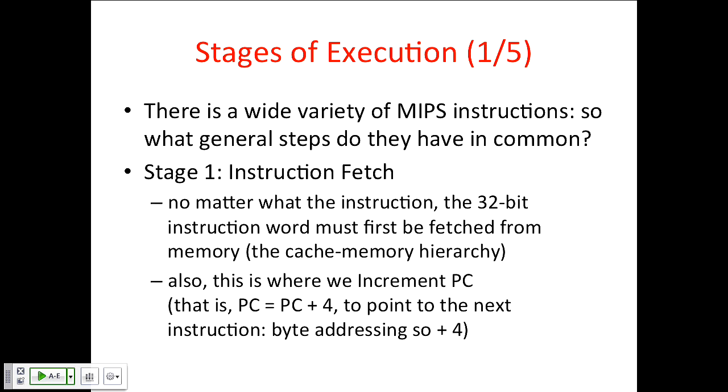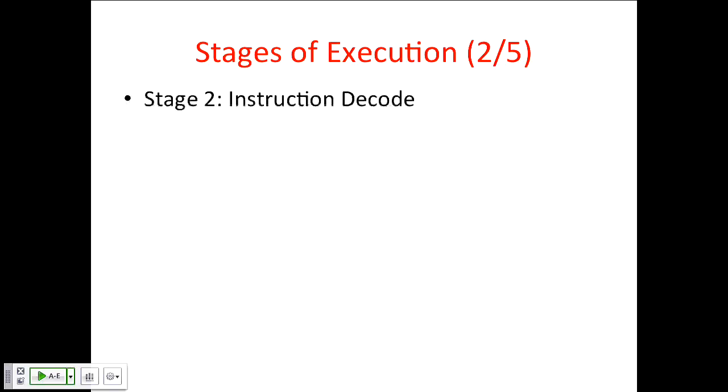Now, instruction fetch: you have to fetch every instruction, right? That's stored in program memory. Every instruction has to go through that stage. Also, every instruction, you have to decode it. So all I've done so far is get the 32 bits from memory and put them in the processor. Now I have to start the work of understanding what I need to do by looking at the combinations of bits, depending on the opcode and the funct fields or the other fields inside the instruction.